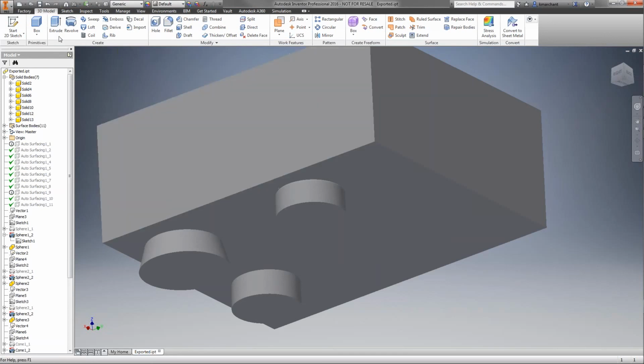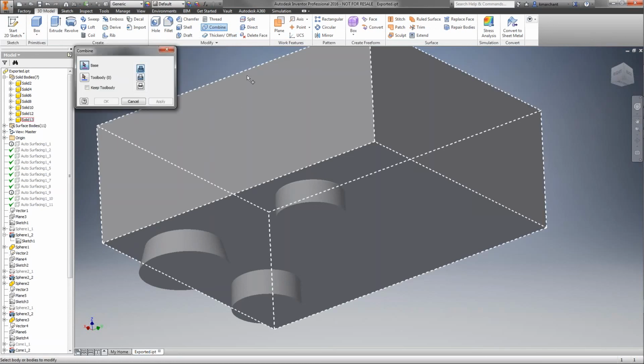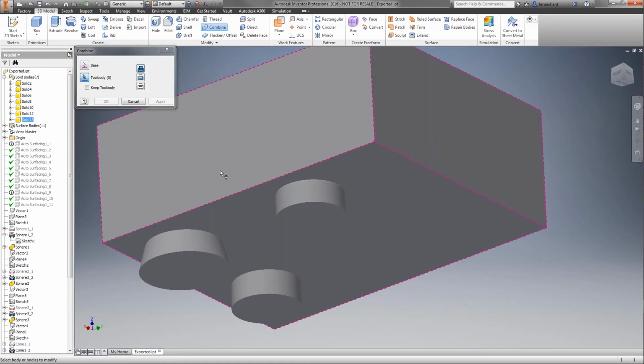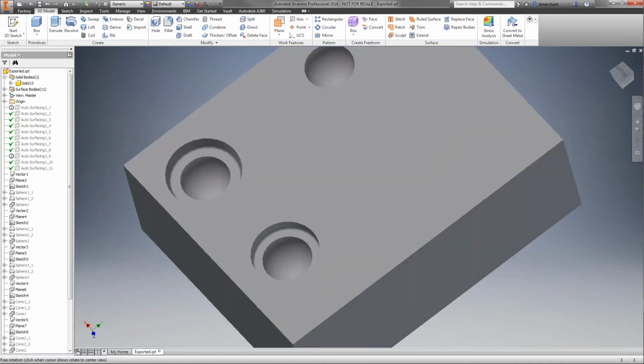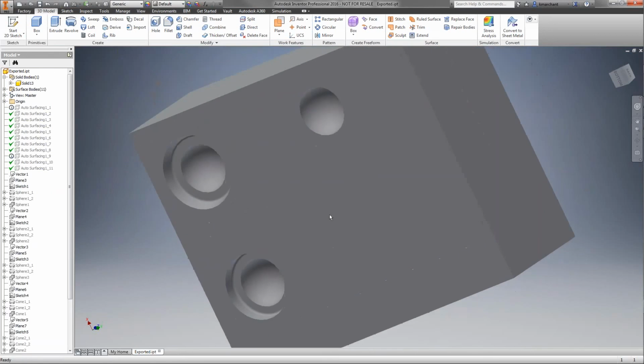And so I'm going to come out here. First I would do a save as, create this new part, so I keep that geometry separate. Today I'm okay with that. It didn't take me long to create it. So I'm going to come in, I'm going to combine. Use this combine tool. I'm going to select my base, and then my tool bodies are going to be every other solid in here. And I just want to make sure that I cut these out. Say apply. And now I've captured this geometry that I can now use in my design, whatever that design is, for my purposes.